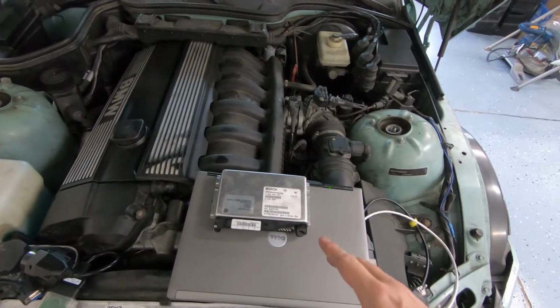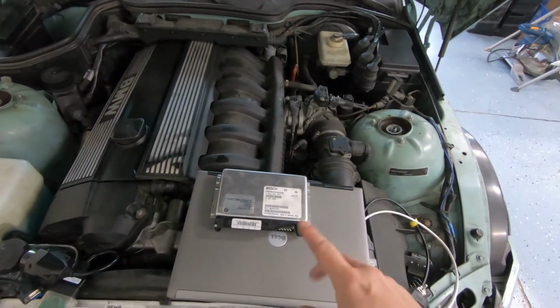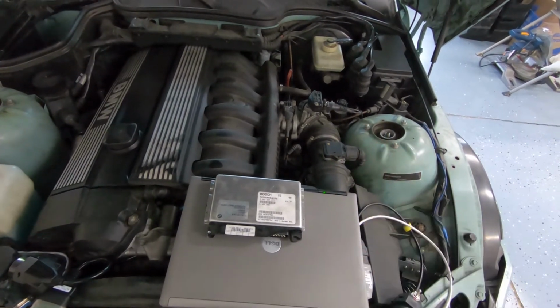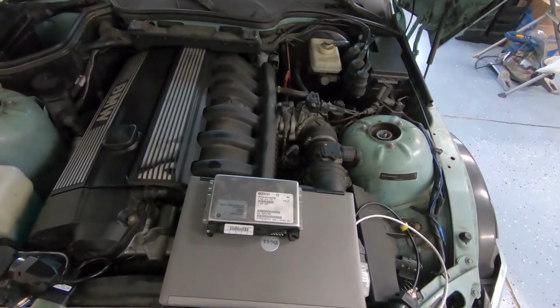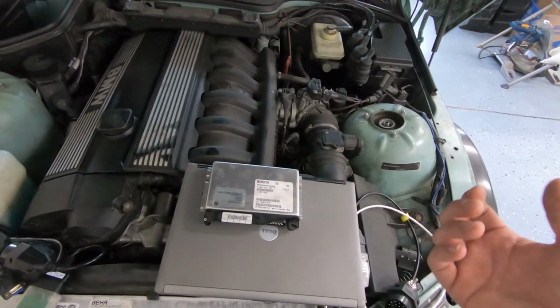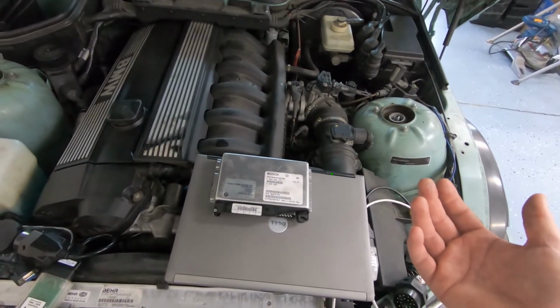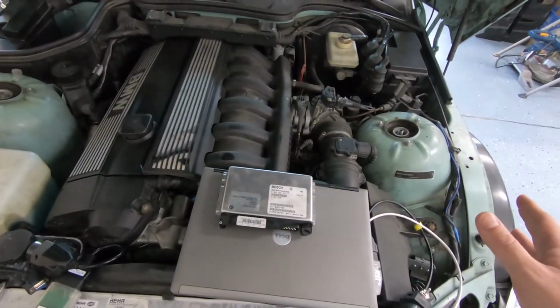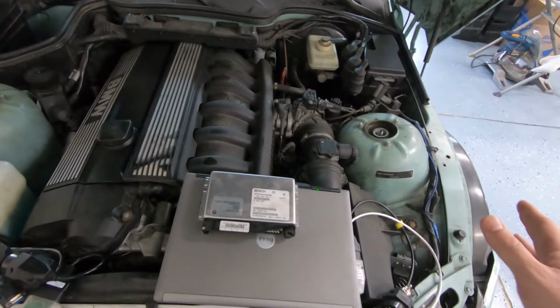And the lights that I had on in the dash were for the ASC, and then the gear for the transmission controller. So that means I didn't have traction control, and maybe possibly that was affecting the ABS as well, but I can't verify that because I didn't have a scenario where I activated ABS.